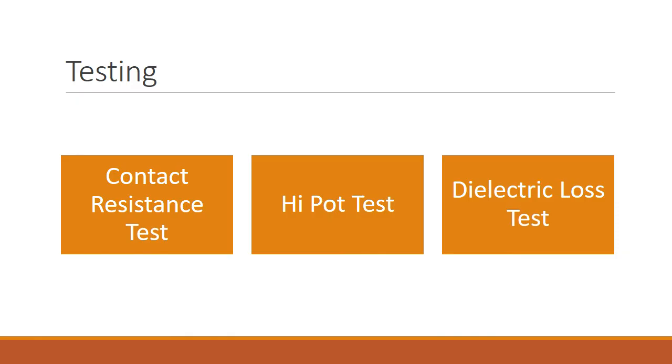Next up is the high-pot test. The phrase high-pot stands for high potential, which is short for a dielectric withstand test, which is the more technical term for high-pot testing. High-pot refers to a group of electrical safety testing devices. To guarantee that current flows freely from one place to another, high-pot testing is often required. The test checks the cable's integrity and its capacity to tolerate high voltages for a specific length of time.